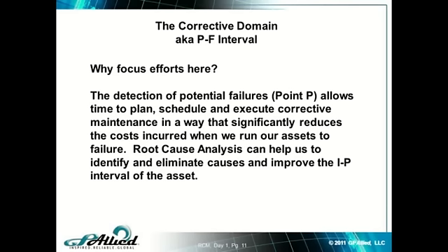So from 18 months to over 10 years, by focusing on what does a proper pump installation look like, what's the foundation we should be using, what type of base should we be using, what type of alignment do we need to maintain between the pump and the motor, what type of support do we need with the piping. By addressing all those issues, designing a good design and installing these things correctly, we changed that MTBF from 18 months to over 10 years.